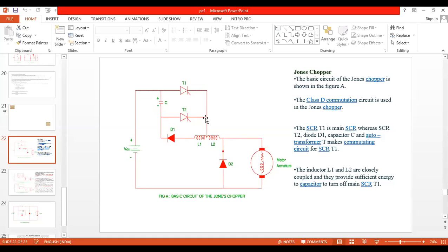From T2, it never flows through L1 because they are completely energized. They have certain resistance also. So current flows where the resistance is less. We assume that when the SCR is on, its internal resistance is approximately equal to 0. Therefore, 100% of current enters the cathode terminal.